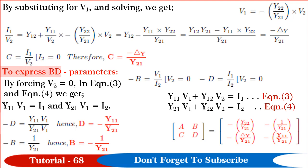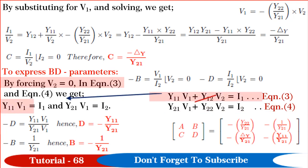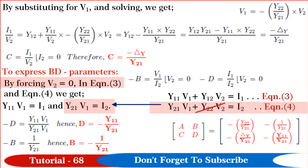To express B and D parameters, we know minus B is equal to V1 divided by I2 when V2 is equal to 0 and minus D is equal to I1 divided by I2 when V2 is equal to 0. So, by forcing V2 is equal to 0 in equation 3 and in equation 4, we get Y11 V1 is equal to I1 and Y21 V1 is equal to I2.